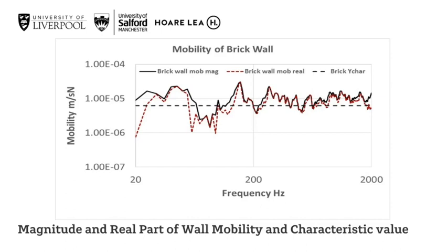And also the differences are not that high. They're well within a decade. So they're around the region of 1e to the power minus 5, the measured and the characteristic mobility. So this is a really powerful example of how you can use your characteristic mobility as a powerful tool in your predictions or in your design for any purpose related to structure-borne noise prediction or vibration prediction.